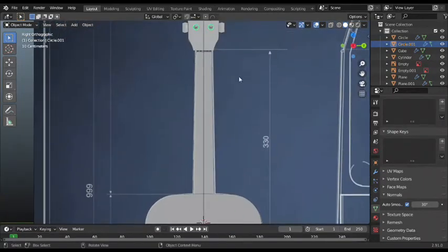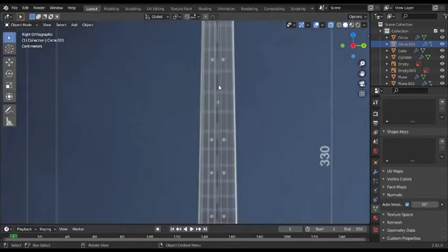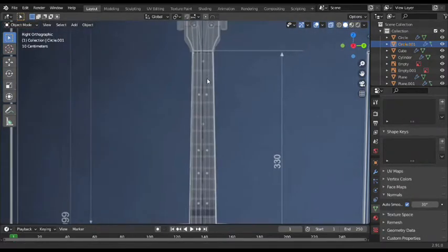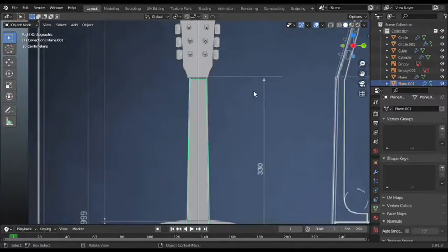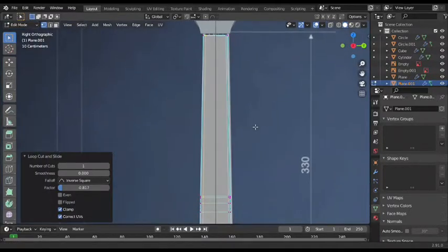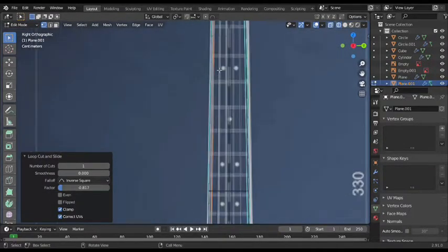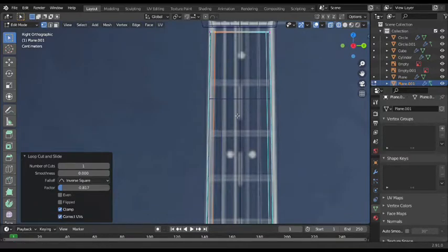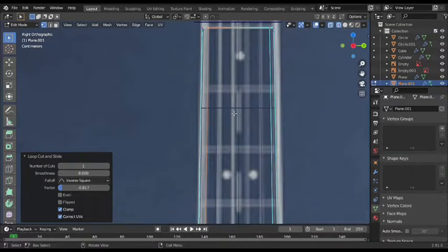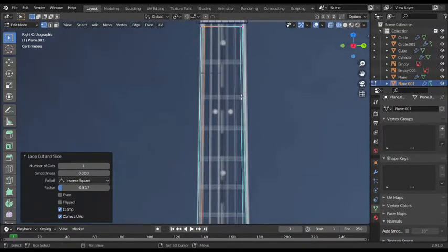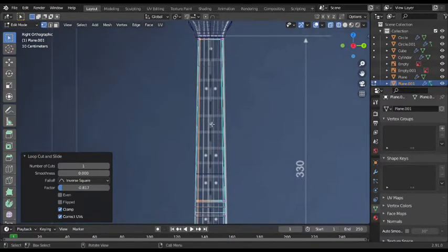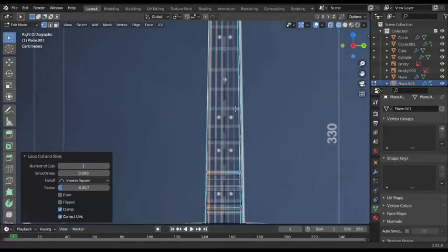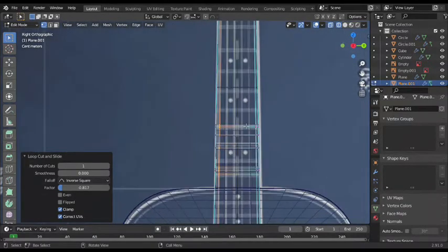Now I think I'm gonna add some lines that were given in these lines, so this is gonna be very easy. So I'll select this one, tab into edit mode and enable the X-ray one, or let's just say I'm gonna switch to wireframe because that's way easier. Okay, so all we need is to simply put some parallel loop cuts and extrude them a bit so that they will give a bumpy bridge like figure which we are in need here.